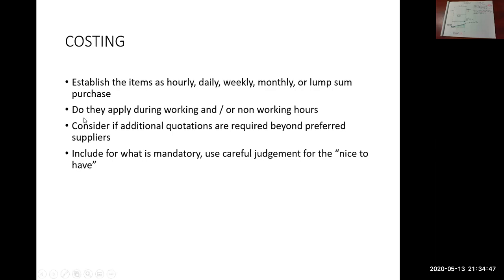So do the costs apply during work hours only, or do they apply after shift? For example, if you have a generator running maybe a dewatering system, that generator needs to run 24 hours a day because your dewatering needs to be maintained on a 24-hour basis. Conversely, if that generator is powering your site office, maybe the generator only runs while you're working. So maybe it's 8 hours a day, maybe it's 10 hours a day.